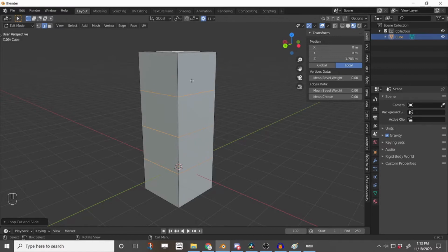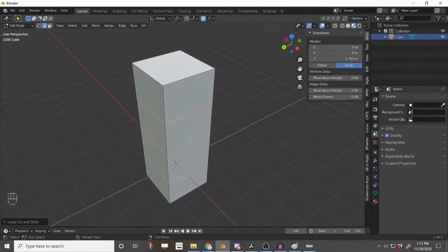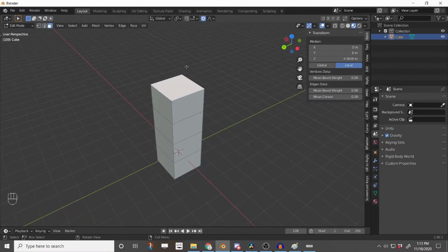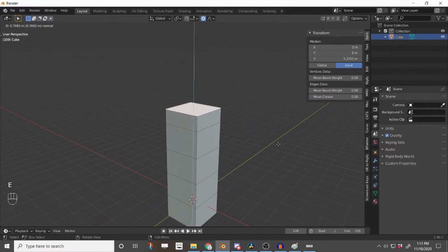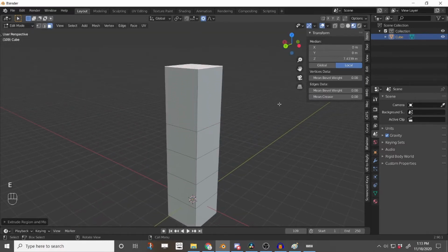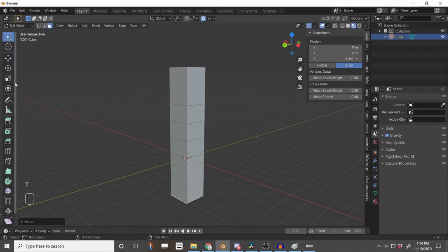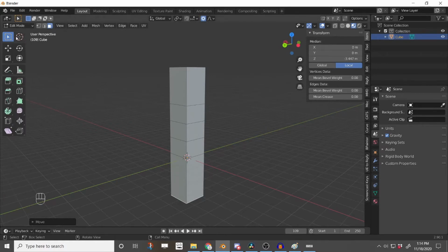The next thing that we need to learn is how to extrude things. Now, if you press 3 on the numpad, it'll take you into face select mode. And I will click this and I will press E to extrude it. You can remember that by E. Now, these are the hotkeys for it. But if you wanted to use tools, you can press T for tools. And I'm just going to push it just a little bit here because I like having this kind of fat menu, not the long menu. And extrude is right here.